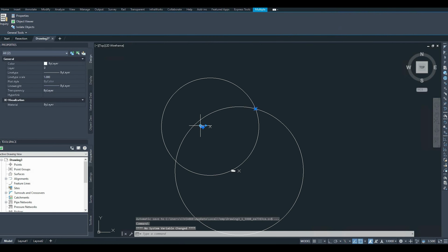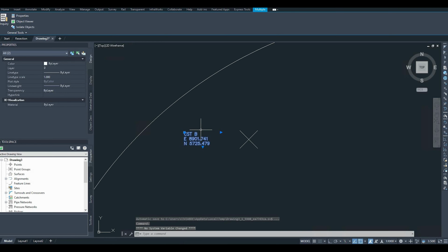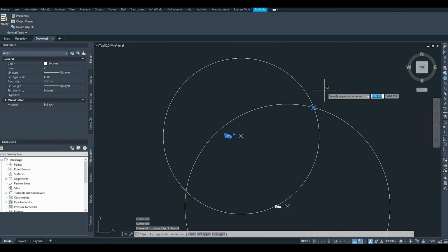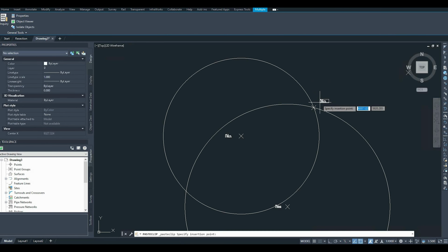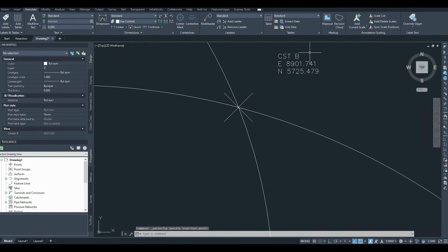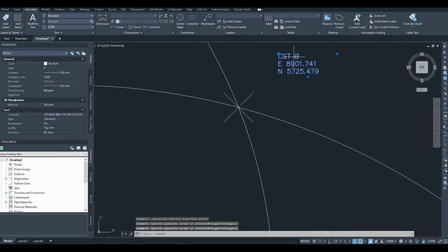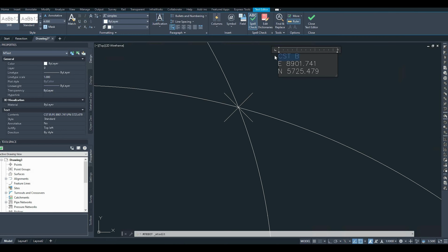Now you can add, of course, the coordinates here. Just I will get this, copy it, Control C, and then go here and paste this, Control V. Very simply, this is the location, for example. I would paste it here, and then you would say here, for example, give it a description. Yeah, I would say, for example, secondary control station. And you can call it whatever you like, for example, G. And then you would just write down the coordinates, the easting of the secondary control station. Let's call it 9321.427, and the northing of it would be